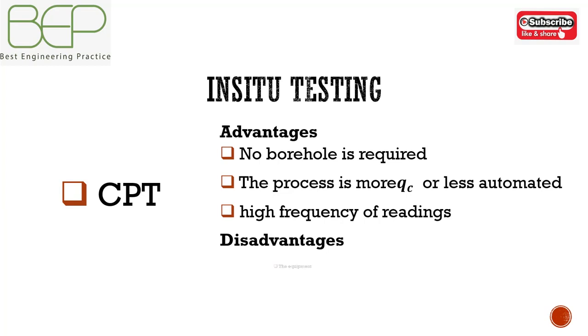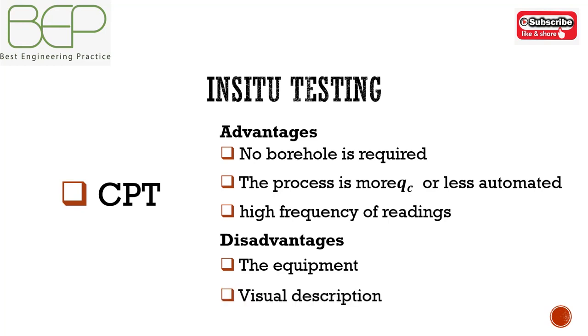The equipment cannot always penetrate the ground to the depth envisaged, as obstructions such as dense gravel, cobbles, and boulders can cause refusal. No sample is obtained for visual description. The common methods of sampling and in-situ testing used during boring and drilling are described.